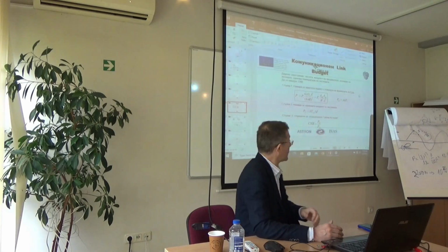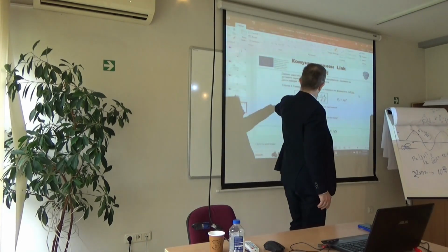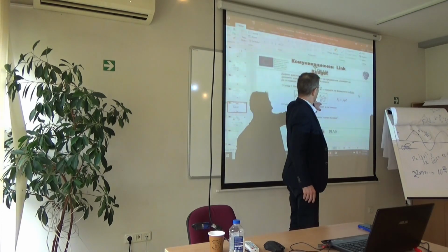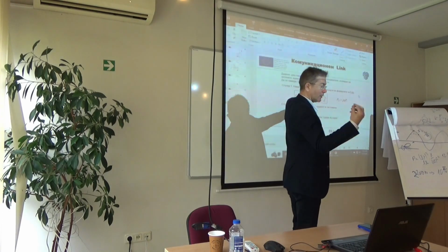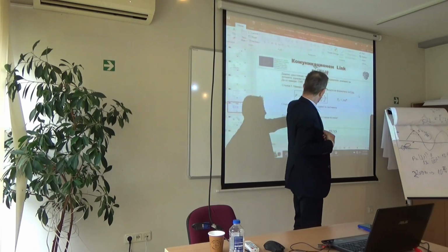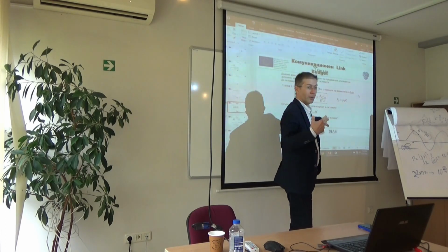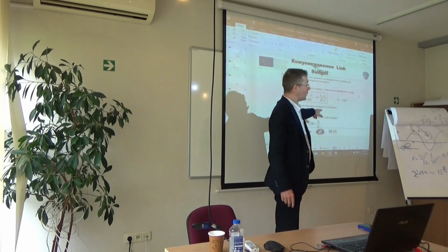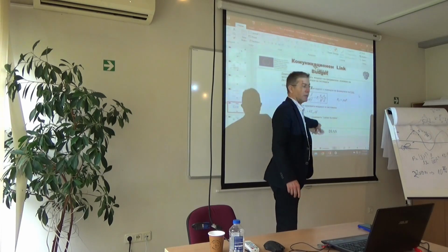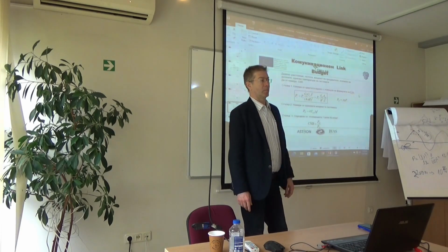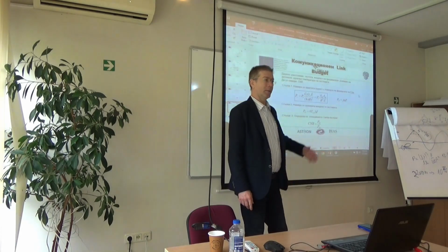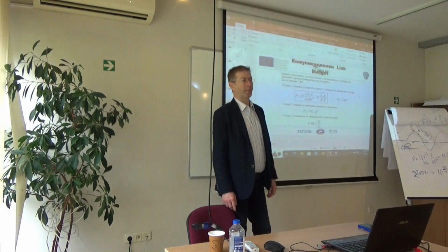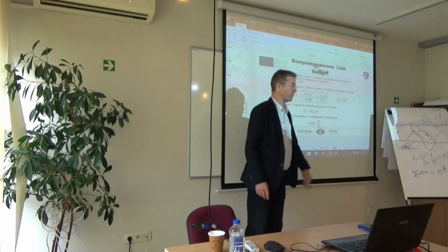The communication budget is when we add all the power coming from the transmitter and the receiver, and then we add all the noises that we already spoke about, kT and frequency bandwidth, and when we divide these two, we receive the carrier to noise ratio. And this is what actually does our job. C2N, carrier to noise ratio.